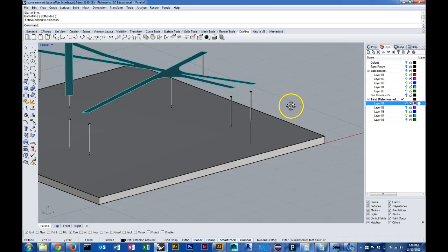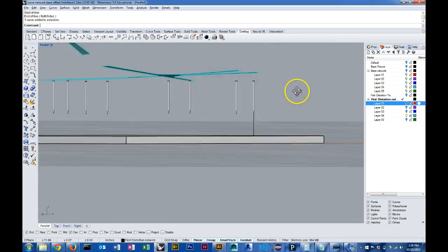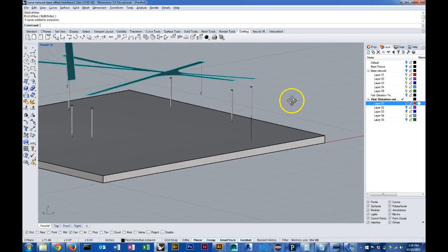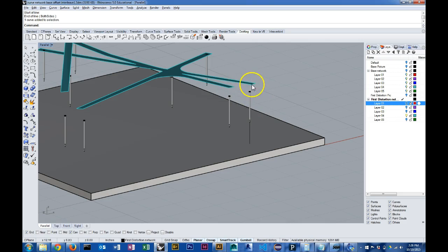Okay, now that line represents the relationship that I want this to have with the curved network layer. So I'm going to grab both of those and start moving that up, and then I'm going to grab the bottom of that line. Well, I have to grab both of these, but then move vertical, and I'm just going to snap that to there.